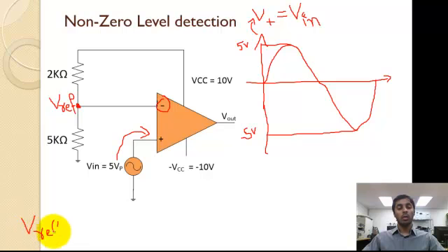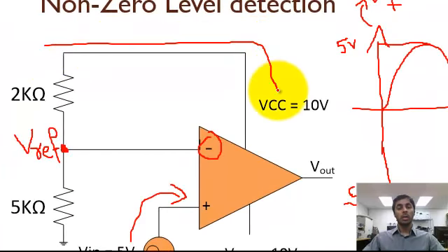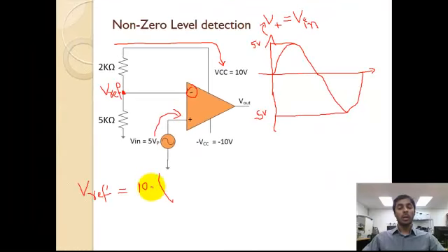As you are already aware, the voltage at that point is the total voltage coming in, which is the 10 volts, because this voltage divider is getting the signal from the 10 volts. So the total voltage is 10 volts times the 5K, because V reference is with respect to the ground, which is across the 5 kilo ohm resistance. So the 5K is going to be on the numerator.